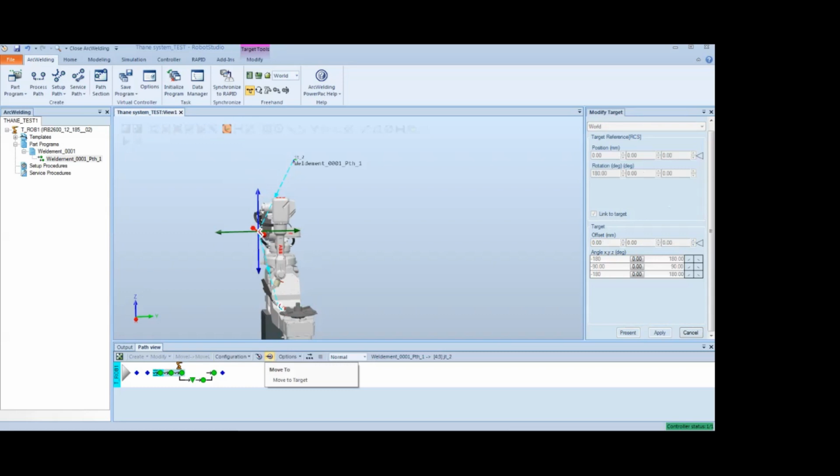If I create multiple move instructions on my approaches, I like to set the motions to a linear instruction as I get closer to the weldment. The linear instructions base their motion on the configurations and orientations of the previous target, making them more repeatable and controllable. If I am not approaching singularity, those linear instructions should work fine.